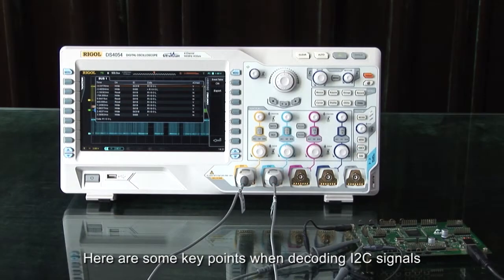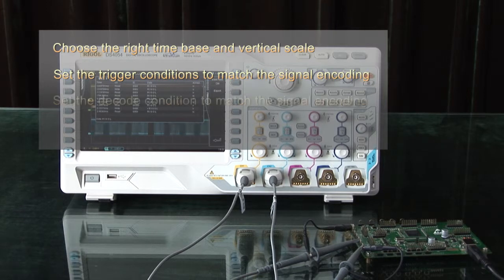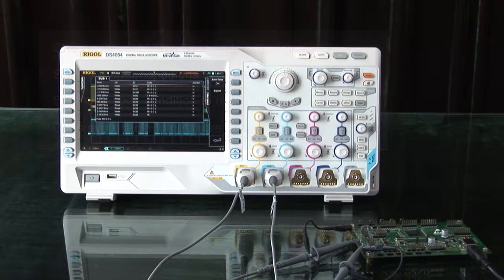Here are some key points when decoding I2C signals. You want to choose the right time base and vertical scale for your signal. Set the trigger conditions to match the signal encoding. Set the decoding conditions to match the signal encoding. Open the event table and you can get more data, as well as store that in USB.